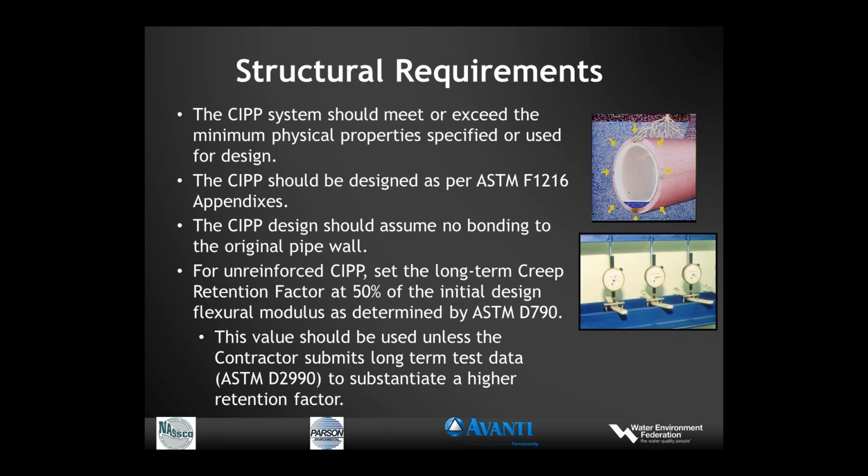This is the way cured-in-place pipe has been designed for decades for unreinforced cured-in-place pipe. And if it's designed properly and installed properly, structural failures are just essentially non-existent. There are failures, but that simply means it typically wasn't designed or installed properly. This value should be used unless the contractor submits long-term test data in accordance with ASTM D2990 to verify a higher value. And also for reinforced products, a reinforced laminate may have a much higher retention.